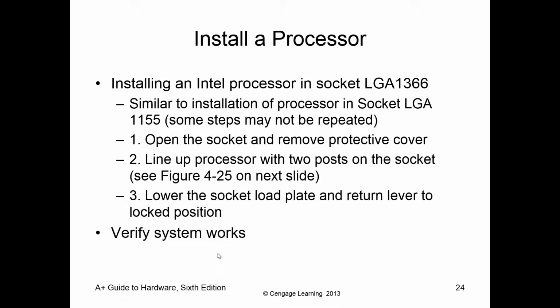Now, installing other variations of the processors, it's the same thing. It's just, again, read the documentation. Do not bend the pins. Be careful. Protect yourself from ESD. And verify that the notches line up and install the new processor.